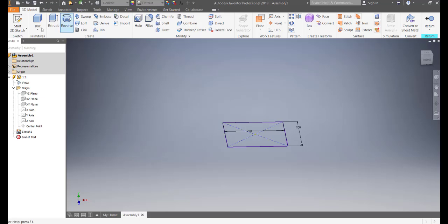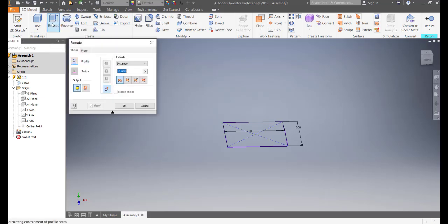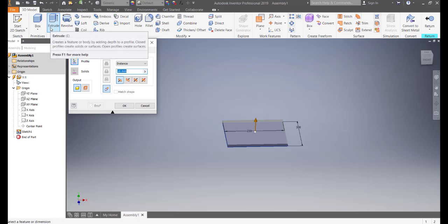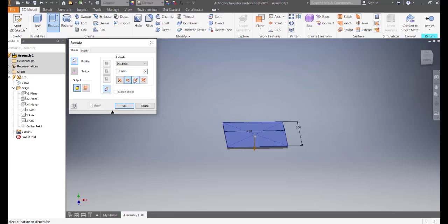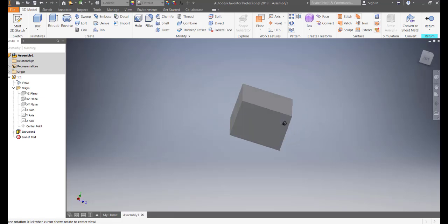I want to have an actual cube. So if you click on extrude, you can have any 3D shapes. For example, you can use this icon to change the direction and the height. Let me set it to 150 millimeters. You can use these icons.